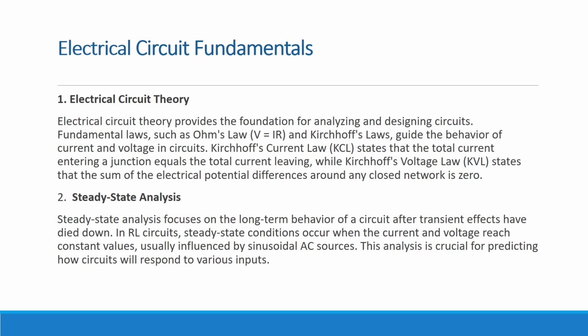Electrical circuit fundamentals. Electrical circuit theory provides the foundation for analyzing and designing circuits. Fundamental laws such as Ohm's law, V equals IR, and Kirchhoff's laws guide the behavior of current and voltage in circuits. Kirchhoff's current law (KCL) states that total current entering a junction is equal to total current leaving the junction, while Kirchhoff's voltage law (KVL) states the sum of electrical potential differences around any closed network is zero.